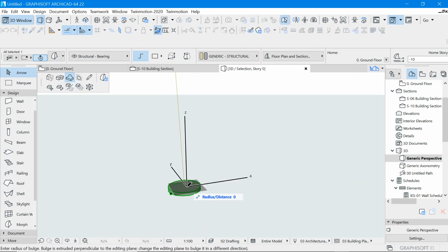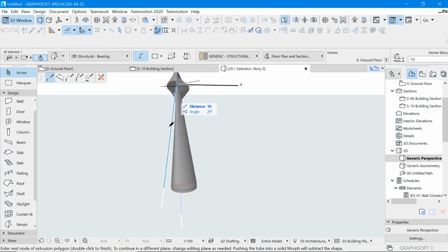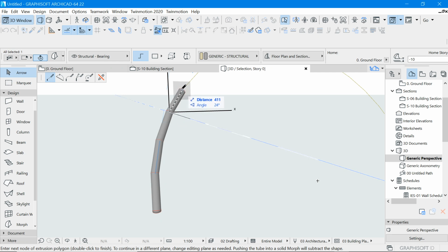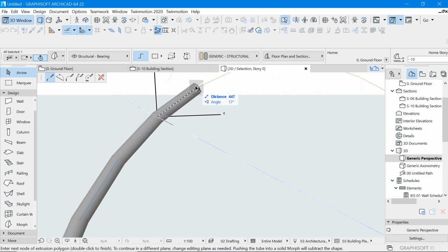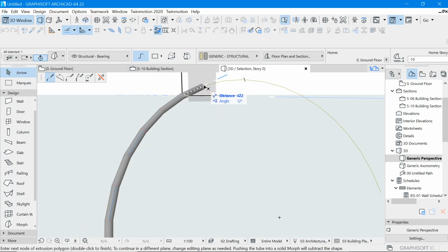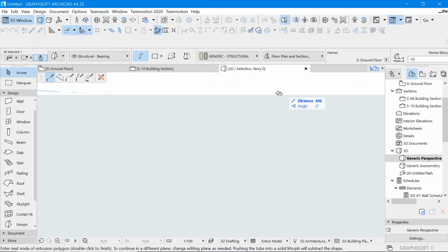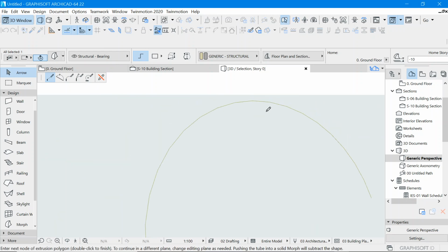Start afresh. Click here. Pick the tube option. Go up by 10. Enter. Then pick the first segment. It's picked. The second one will follow accordingly. Here we have to be very careful, because once you don't hit the right point, then you get a crooked kind of tube.